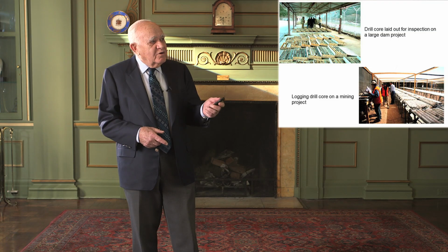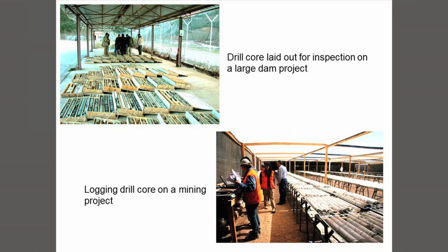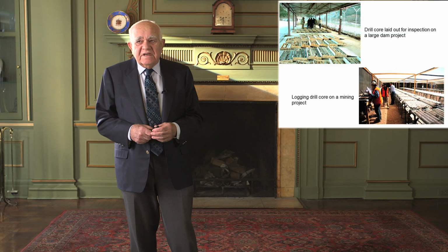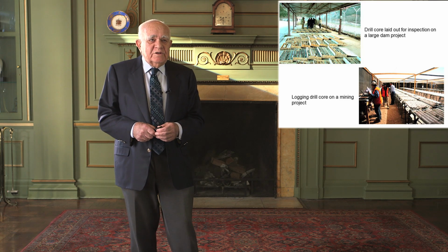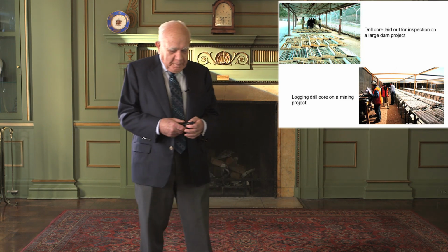So today, in visiting a large project, you would very often see the core laid out, and in the lower right there you see probably several kilometers of core laid out, very high quality core, and that is mapped then to determine the characteristics of the intact rock and of the discontinuities that occur in the rock mass as you drill through it.